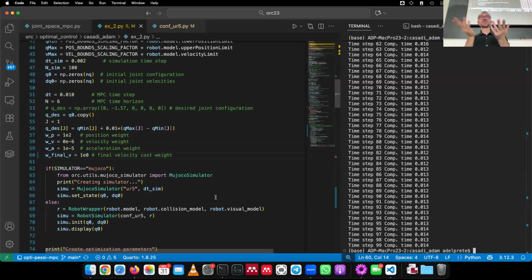Well, everybody can answer, but I mean, since you were the one suggesting it. We are considering a finite horizon, so it's the thing we said the last time. If we consider the finite horizon, we have to compensate in some way the fact that we don't have an infinite horizon, so we put a final cost that simulates the infinite horizon.